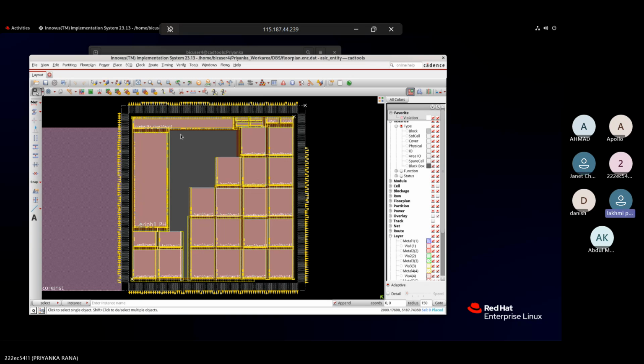So this blockage, even if it is merging, doesn't it harm, right? No problem, because these are temporary ones. We'll remove them. Any DRCs or congestion with respect to blockages, we can ignore because after placement, we will remove them. Oh, okay. Got it.